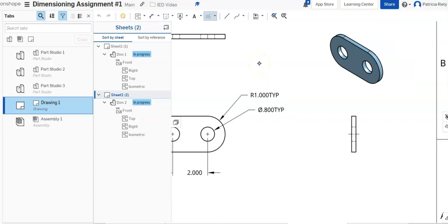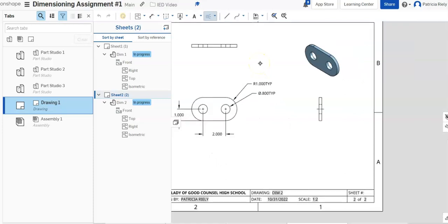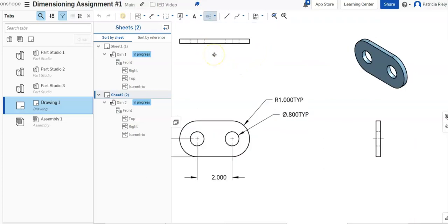Okay, let's do the same thing up here because you need two of them. So I kind of have it, but it's not really valid. So grab this vertical section, that's hidden line, that one, and it puts it there longer. Remember, it has to extend beyond the object lines. Grab this guy, and there it is longer.